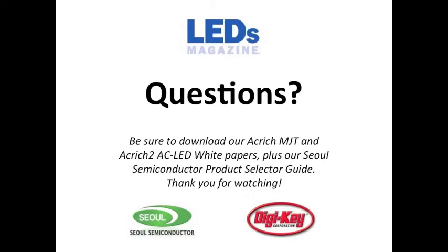No, a 12-volt DC supply. Sure. There shouldn't be any reason why that wouldn't work if you have a specific driver that's going to handle the voltage and current that it needs. It just may be the case that you need either an LED with multiple emitters in the package, or multiple LEDs to get to that 12-volt forward voltage, right? That's correct.